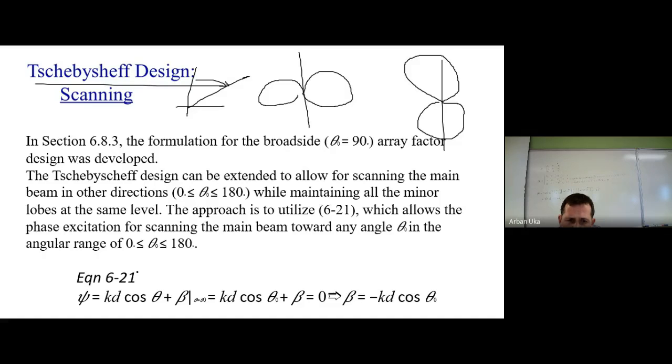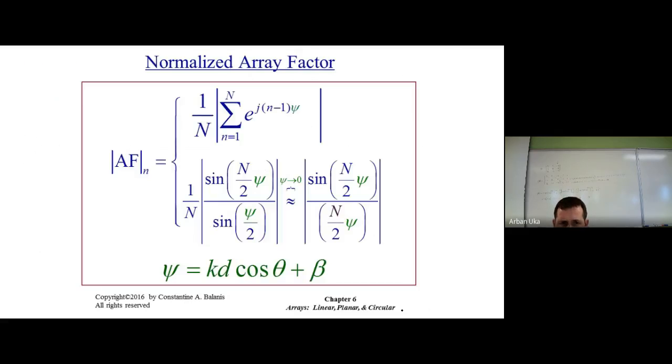In this case, we have to be careful regarding the equations. They are not as simple as we might expect, but this phase difference between any two subsequent antennas to produce this distribution of the power along this specific direction, okay, so this is theta 0, we will have to use these expressions, which we have seen quite a few times.